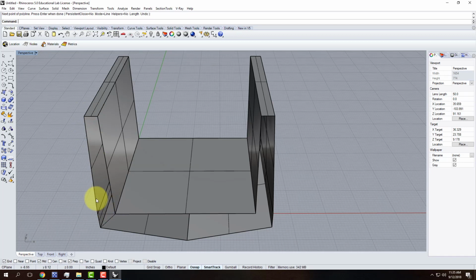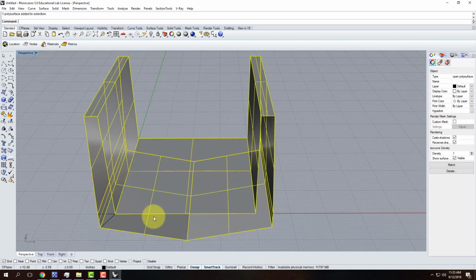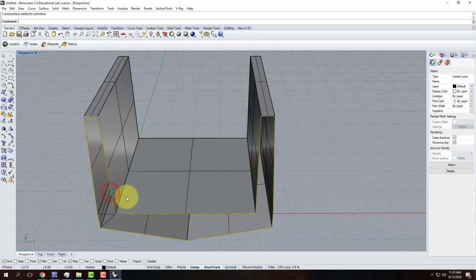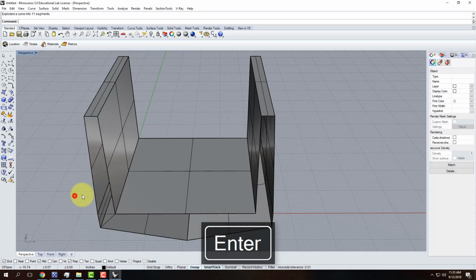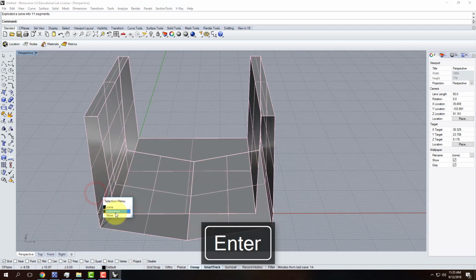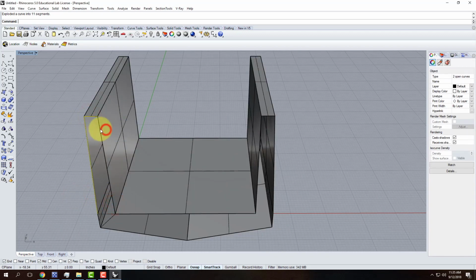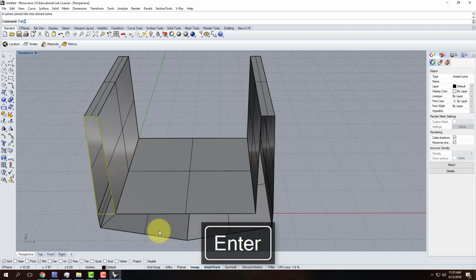Now, what I did in my example was I did patches. So in this case, I had this exploded, and I said, OK, I'm going to take this curve. I'm holding down Shift, that curve, and this curve. I will join them and then patch.